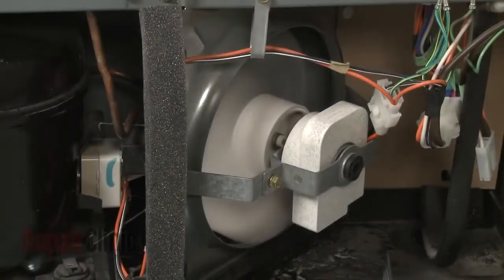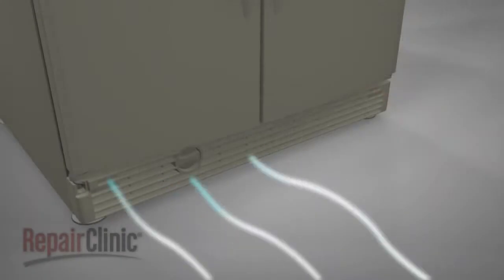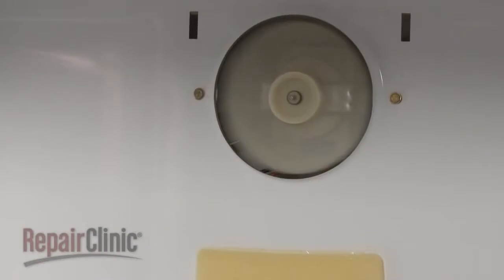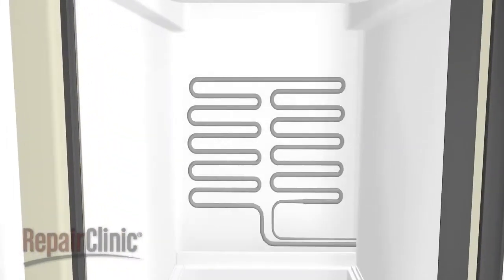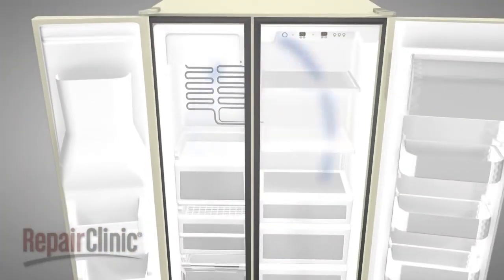Airflow is vital for refrigerators to work properly. To cool the condenser coils, the condenser fan draws in air from the front of the appliance, sends it through the condenser itself, and then circulates the air back out the grill. At the same time, the evaporator fan draws air from the refrigerator into the freezer. The air passes through the evaporator coils, which remove the heat from the air. The air then circulates back into the refrigerator, continuing the cycle.